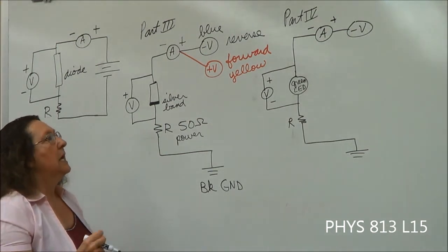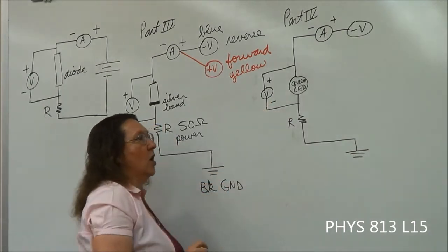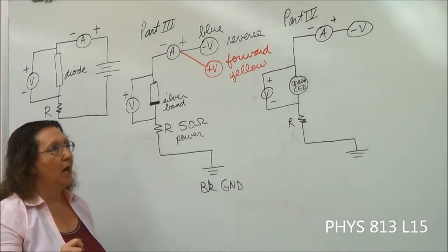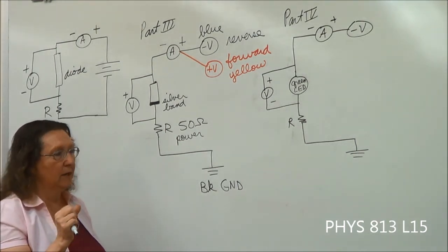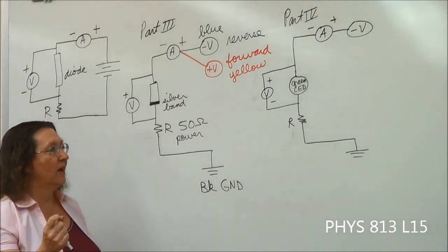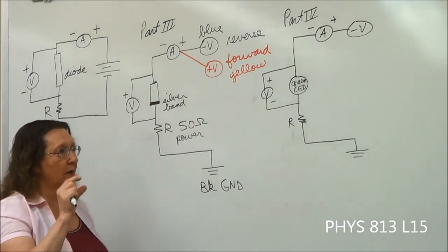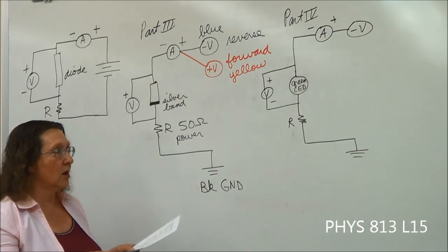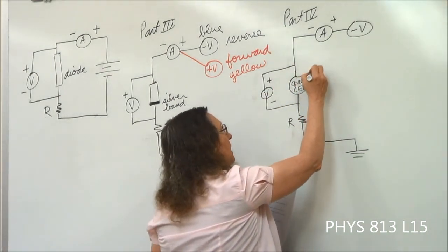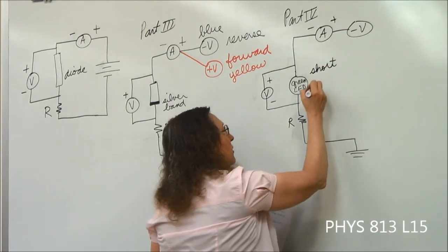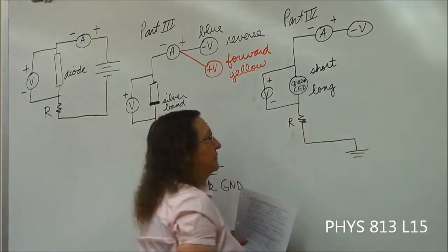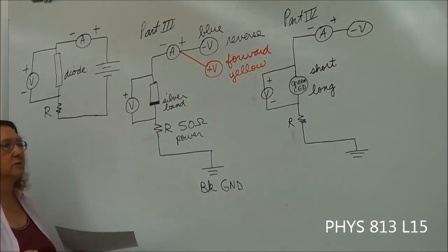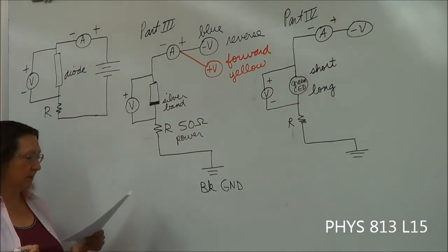But anyway. So now, the thing that you have to look at on the LED, and I'll show you that, is the leads to this are slightly different length. There's one that's a little bit longer than the other. You may have to straighten them out, and most of these that I've sent have been used before, so they're not exactly straight, so you may need to straighten them out. And one lead is a little bit longer than the other one. So what you need is the short one up here and the long one down here. They're only maybe a couple of millimeters length difference, maybe only 1 millimeter length difference.